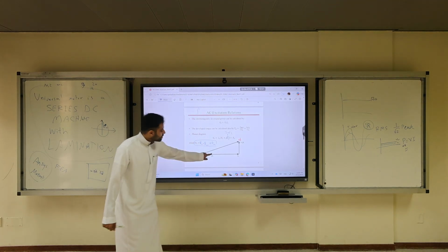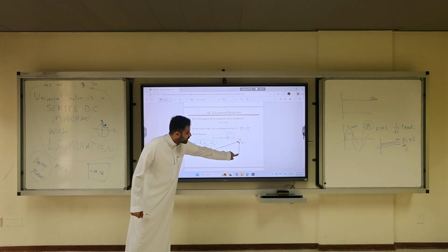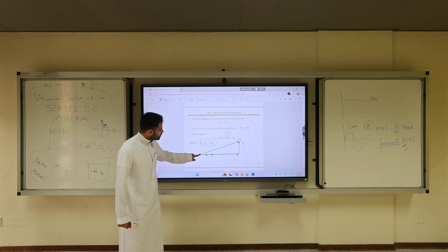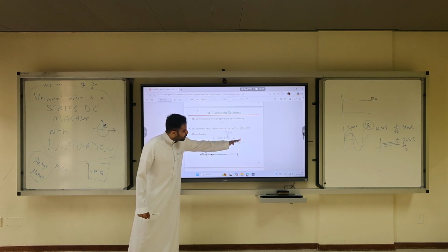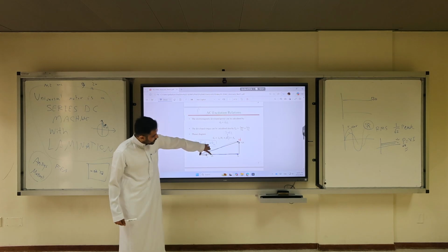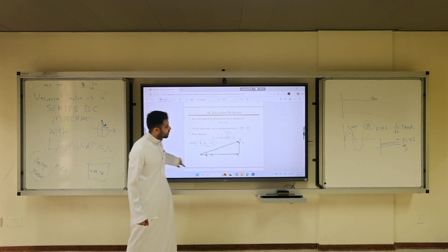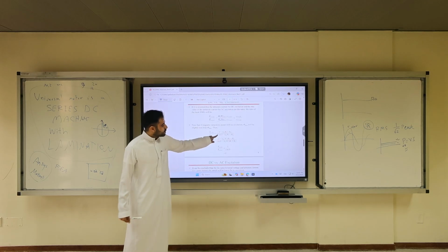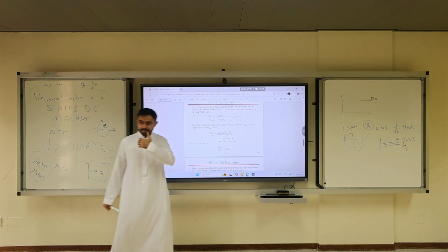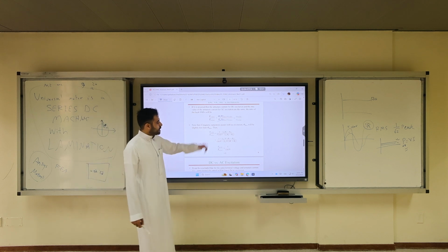Yes. The VT starts from here. Take the VT projection on the X axis. It's this vector, minus IA Rs. It's this vector. So you get the EA. That's why we had V cosine theta minus IA Rs. Clear? Clear. Take the ratio, divide by V.